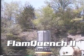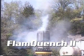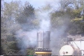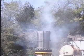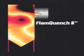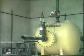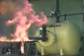Flame Quench 2 has been tested and has been accepted by listing organizations in the United States and Europe. Flameless venting is an efficient way to reduce the maximum explosion pressure for equipment located indoors. Using Fike's Flame Quench 2, process equipment does not have to be located near outside walls to accommodate ducting and can be optimally located. Explosion isolation strategies may be combined with venting or flameless venting to prevent secondary explosions.